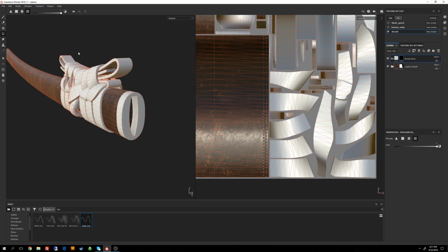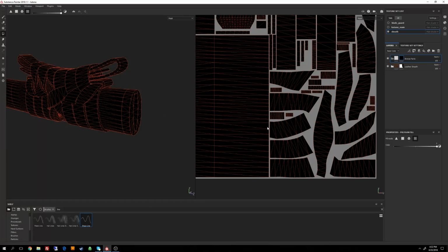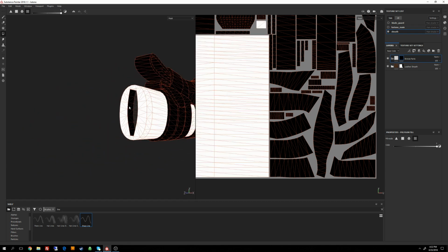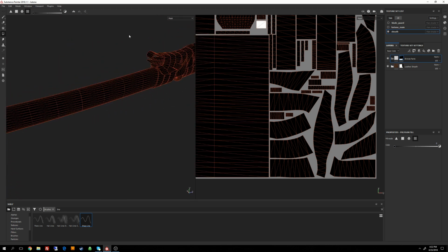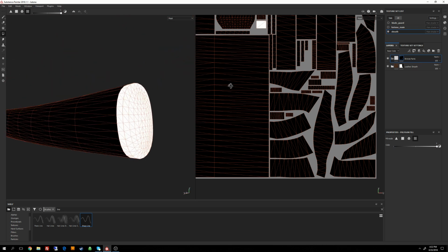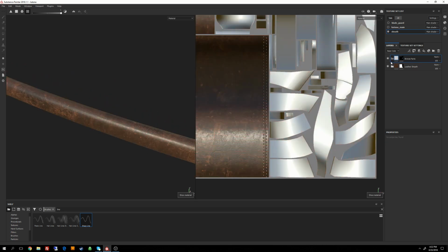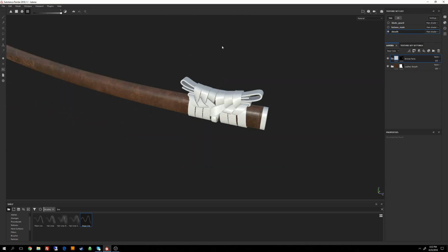Let's go into polygon fill here. You can also paint masks with the paintbrush, and we were working out of paintbrush, so make sure that we want polygon fill as we're selecting our mask here. Let's go into mask mode here and UV chunk fill, and let's select these. I selected that one by mistake, so I'll just drop this to black, deselect that. All right, that's going to do it for those parts. Hit M to go to material mode and switch back to our. We don't need to be working in split view now, so you can hit F2. That'll put you back into 3D view.